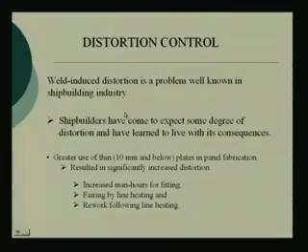I control it right across, and control it in real time. Real time means whenever the welding is being done, such that the distortions are minimized. By control, obviously the objective should be to eliminate, but if not possible to eliminate, at least to minimize. So what we see now is that this is a problem which is well known in the shipbuilding industry.